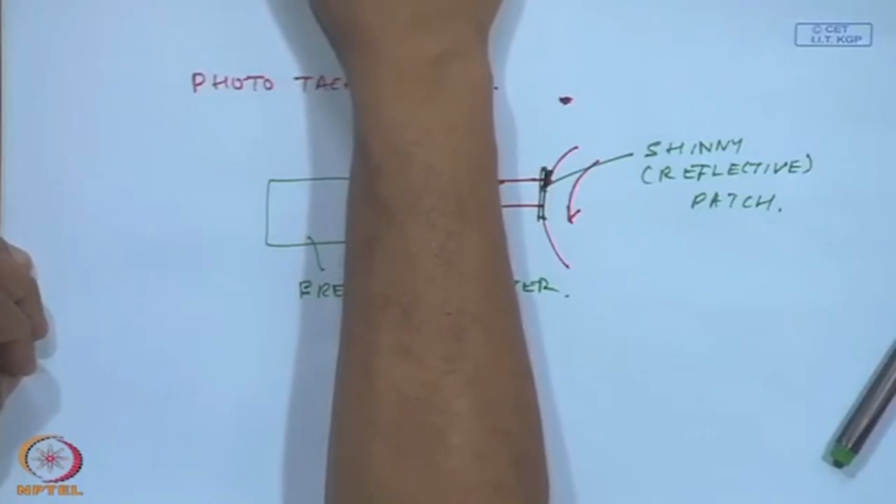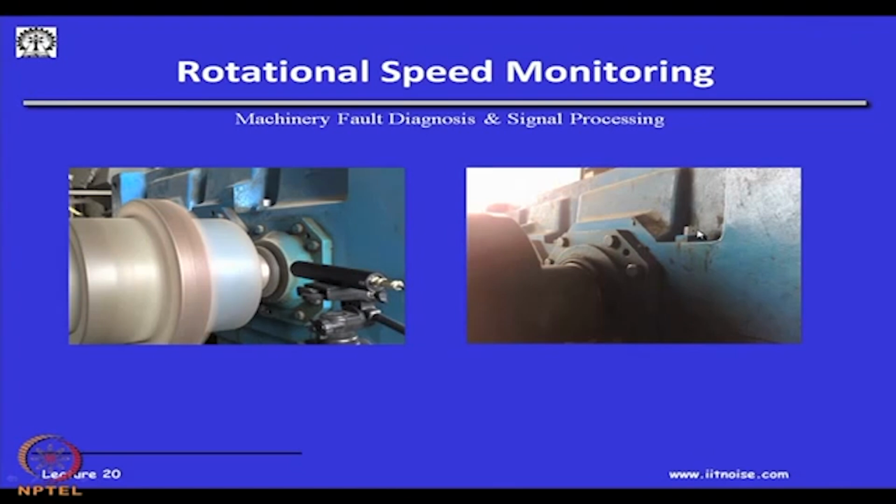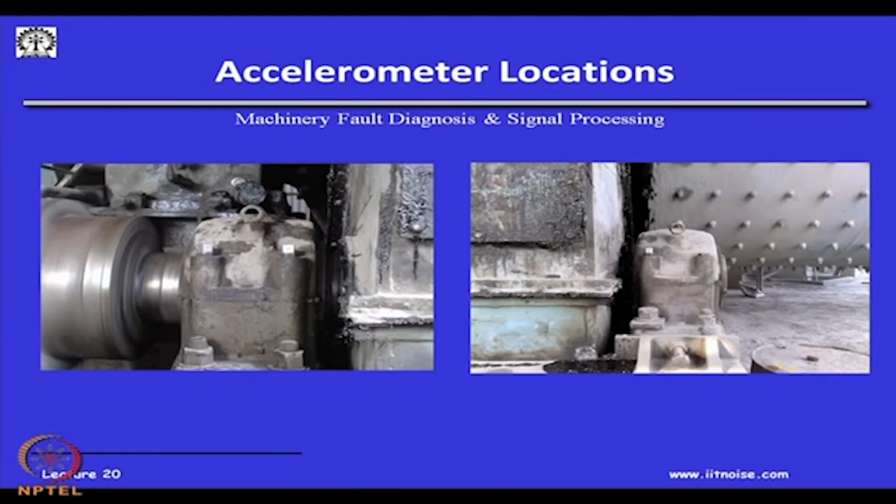Okay. And this is out of a gearbox. Okay. And if you will see here, you can see a shiny white aluminum block. Actually, it's an aluminum block, wherein this is the casing of the gearbox. It is not possible to tap it at this site. So, all we did was put a mounting block and glue it with a cement. Okay. And if you will see a couple of holes here, one hole here and a stud coming out on this accelerometer block, we can screw on the accelerometer to measure the acceleration. I will show you another view.